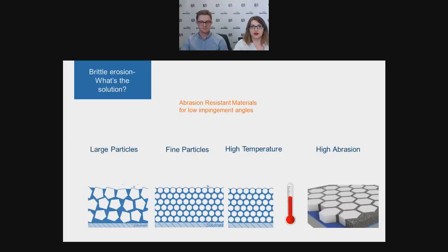And we have a range of hard-wearing lining options, which have been optimized for both dry and immersed abrasive service. So for dry abrasion, there is Belzona 1811, used for large particles, such as those found in the mining and quarrying industry. Belzona 1812 is a modification of Belzona 1811, and this gives protection against much thinner particles. A good example of this would be in pumping equipment involving water and small solids.